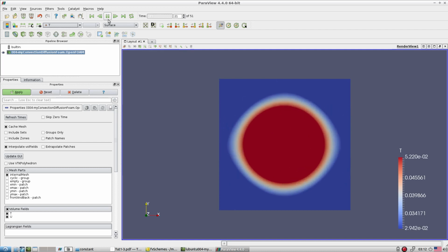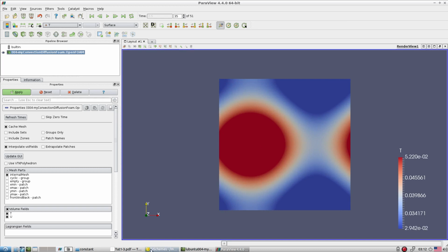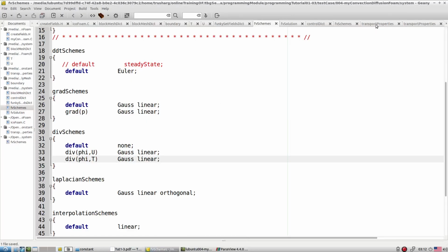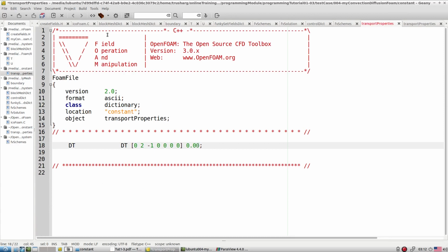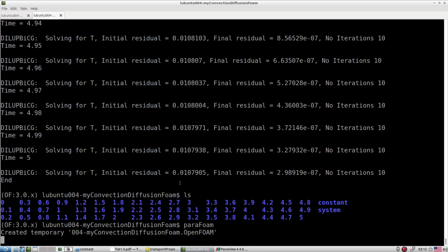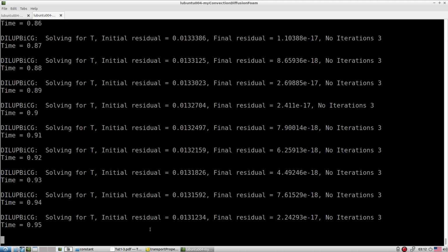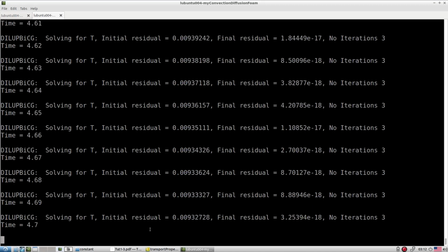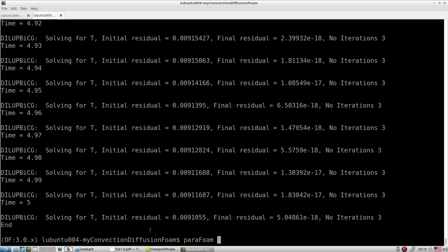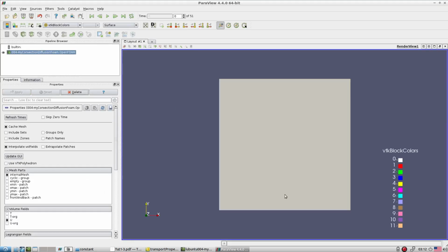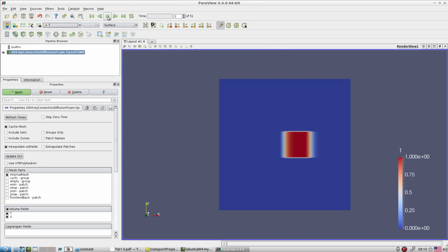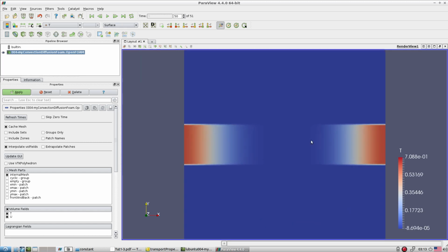If we try to turn off that diffusivity, what it means is, if I say this value equal to 0, then just check again the simulation we run. This time we say diffusion equal to 0, so it is like pure convection, no diffusion at all. This is now pure convection without any diffusion, but whatever diffusive nature we are seeing is because of the numerical diffusion.